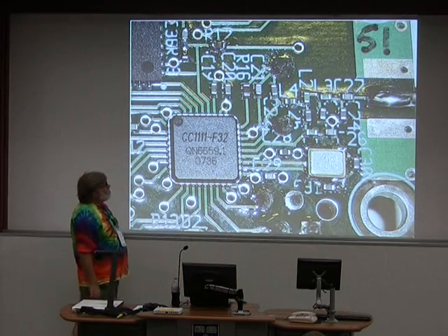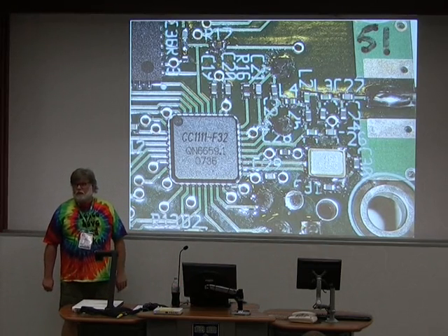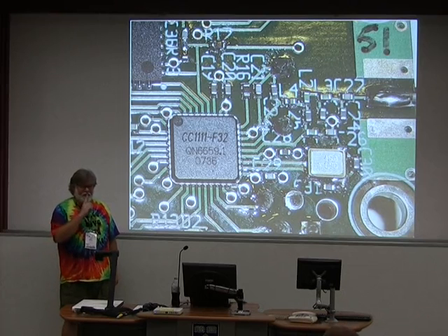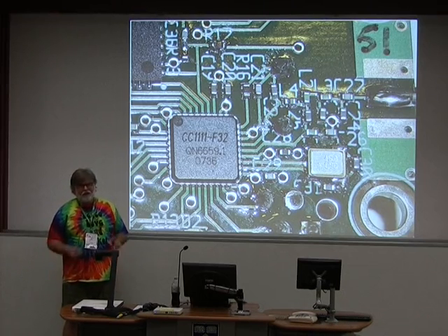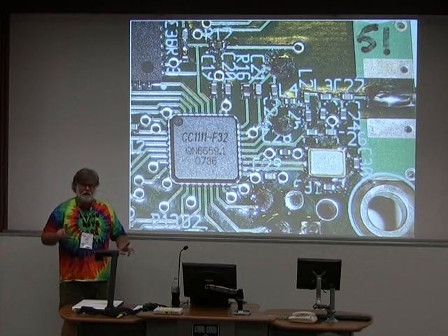There are a couple of other interesting little tricks. How many of you have ever actually designed an RF board of any kind? So one of the tricks to making them work is to not put a whole lot of inductors adjacent to each other, because they'll couple to each other and mutually interfere.